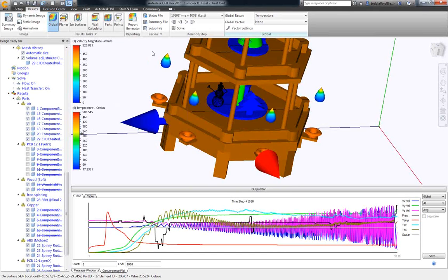I guessed at my heat load. That was another thing that I had some problems with, is I was seeing temperatures going really high. I just did some Googling for how much heat is coming out of a candle. And I saw that it was between 500 and 600 degrees Fahrenheit, depending on your candle. And somebody had said 15 watts, roughly. I think right now I have it running with either 5 or 10. I had to tune that value to try and make it look a little bit more realistic where I'd buy the results.